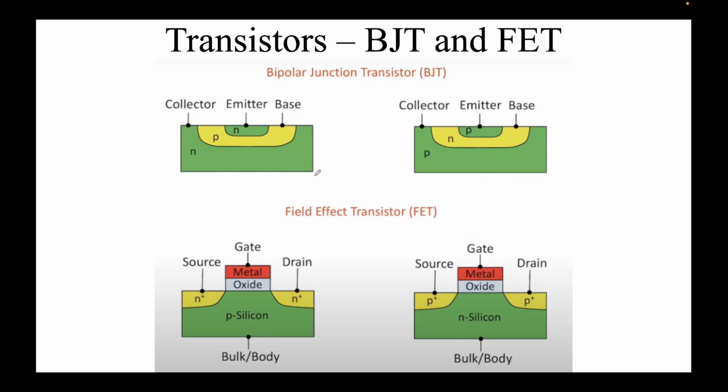The two flavors as we are talking about, the NPN, right? Emitter is N, base is P, collector is N. So this is an NPN BJT, and this is a PNP BJT. And you can also see, I have not denoted the doping here, but you can see the area. So for instance, the collector always has a much larger area, and you see the thin base, because the electrons have to travel from the emitter to the collector.